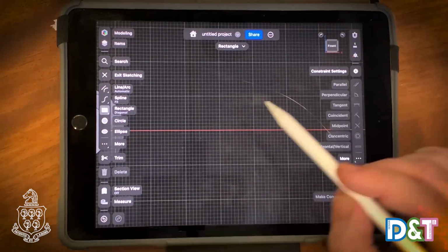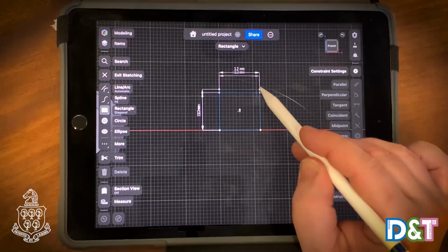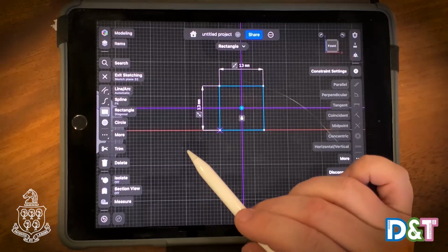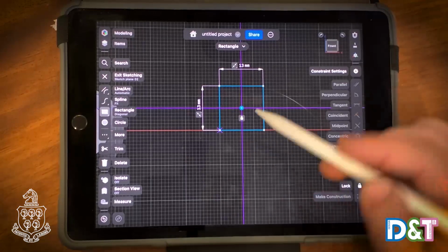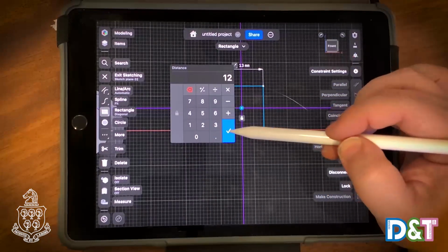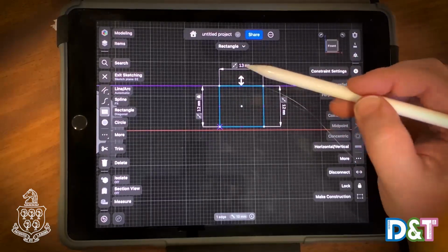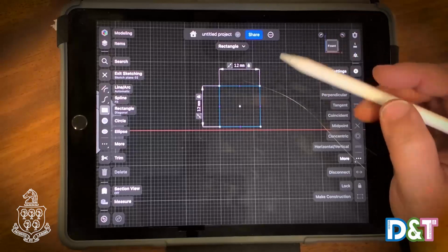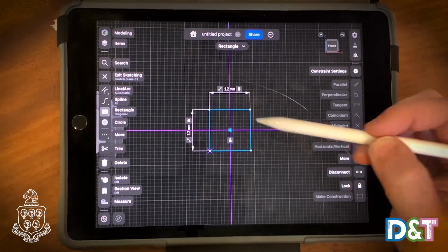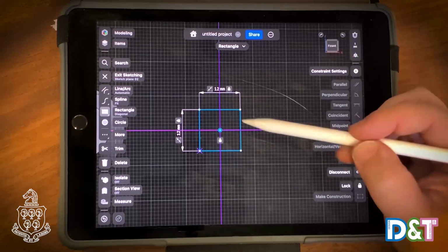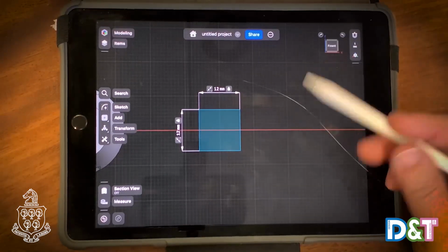rectangle for this one. And then on this middle axis line again, I'm going to start to draw a measurement. For this end, I'm just looking at the diagram to see what size we're at. It's going to be a 12mm square. So we're going to hit 12 on this side. I'm just going to hit this top edge and go 12 as well. Perfect. And like I said, I always like to bring it right down onto the line just so I know exactly where I am, like that, and exit sketch. And we've got a nice square there, which is 12 by 12.